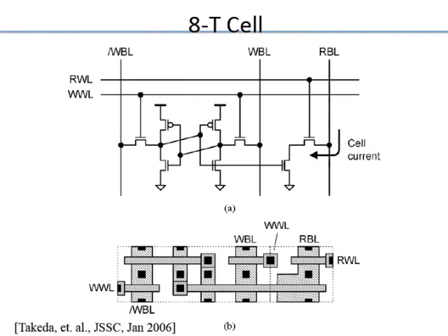And remember, when we say failing of the memory, we are concerned about failure of the memory when you have millions of these cells. Maybe one or two cells might fail, so you want to ensure that the yield of a memory cell is very good. One cell might work well in your simulation, but you're looking at the whole ensemble of cells across your plus minus 5 sigma variation, which should work well, should have good noise margins. At that time, you basically look at these alternate structures, right? When your read noise margins are poor, because you have current going through the cell, you look at these other ideas.